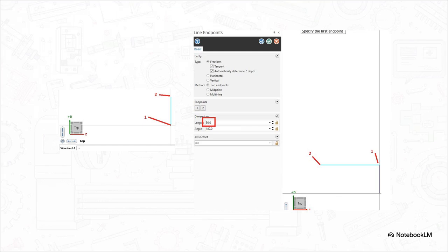Mastercam is incredibly fast for drafting if, and this is a big if, you use your keyboard efficiently. Once you click your 0 origin, whatever you do, don't try to manually drag the line until it looks like the right size. Don't do it. Instead, just type your target diameter, which is 48, directly on your keyboard and hit Enter. Boom! Your vertical line is perfectly sized. Then, to make that 50 millimeter horizontal step, just click the top of the line you just made, drag your mouse a tiny bit to the left just to show it the general direction, and type 50. For that final total length, you can literally just type in the absolute coordinate, Z100, hit Enter, and the software instantly snaps the endpoint precisely to the negative 100 millimeter mark on the Z-axis. It's like magic once you get the hang of it.